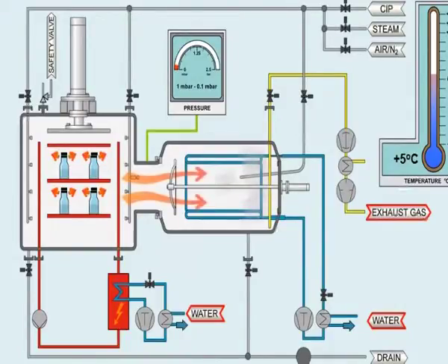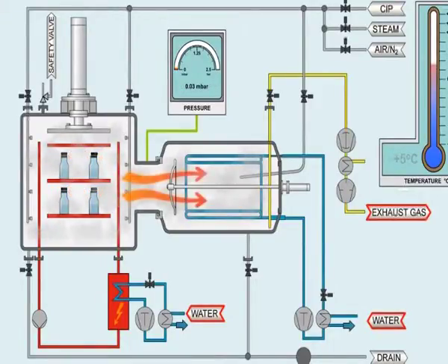Third step, primary drying. It means sublimation of ice under vacuum. The temperature and pressure should be below the triple point of water, that is 0.0098 degrees centigrade and 4.5 mm Hg, for sublimation.